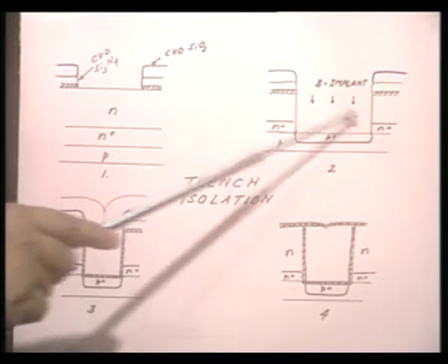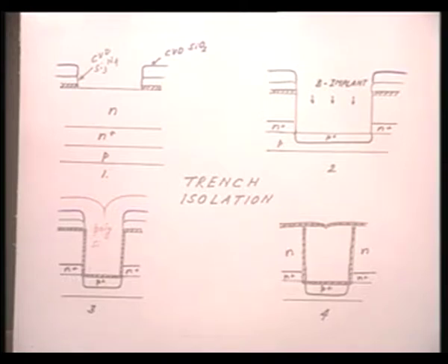Now you have your trench. So, in trench isolation, this was essentially the first step, to etch the trench. What should we do next? We should fill the trench using a non-conducting material. So, we fill the trench by undoped polysilicon. We simply deposit undoped polysilicon, but prior to this polysilicon deposition, notice that a thin oxidation step is carried out. After the boron implantation, you carry out a thin oxidation.